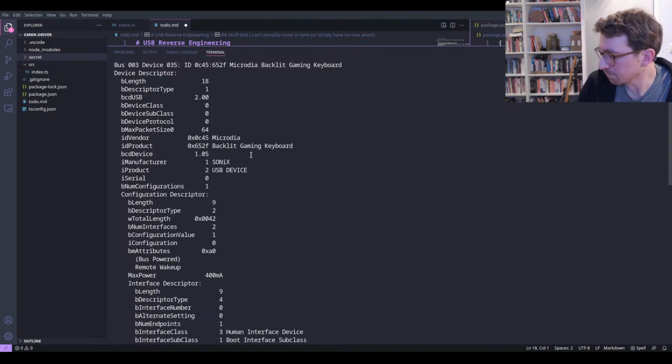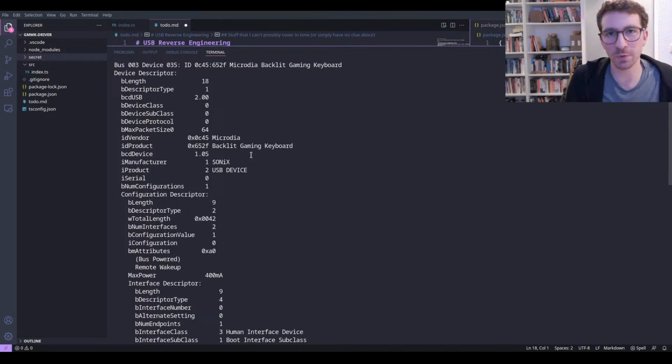So a USB device, when you plug it in, is required by the operating system to be able to ask for these descriptors. And it does that through the signaling level connection with the device. Then the device has to return this information. And this is all standardized. So if you go and read the USB specification, you will find exactly this breakdown.